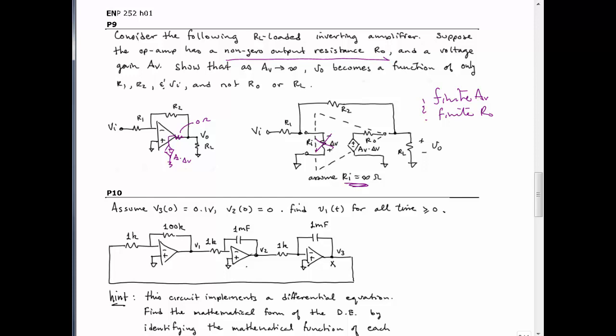And actually all we have is an R1, an R2, an RO, an RL, and a voltage-controlled voltage source, right? And that's stuff from third week of circuits. The only difference is maybe there's more nodes in there than you would have been comfortable solving early on in the circuits course.